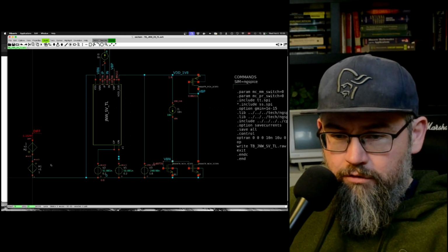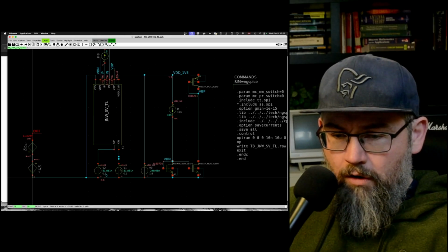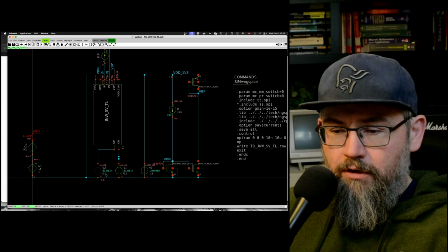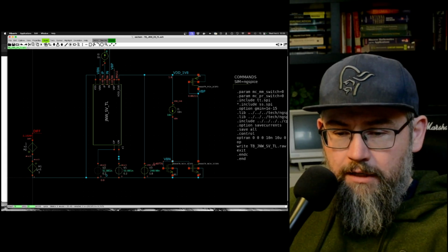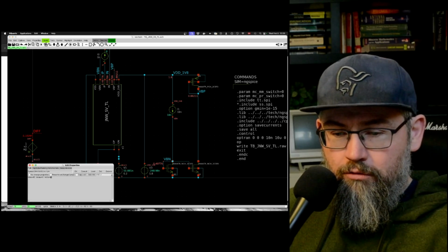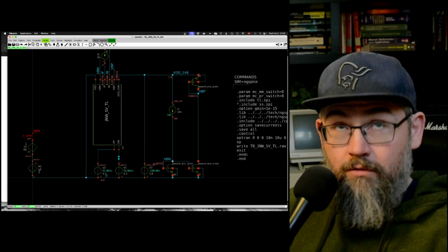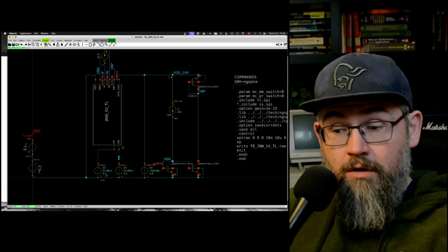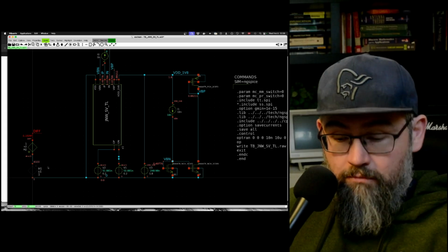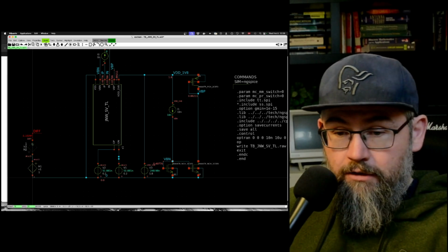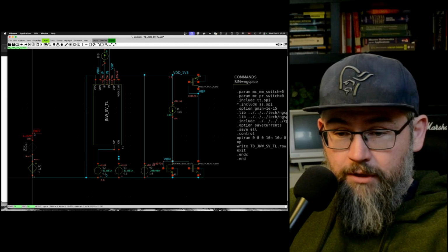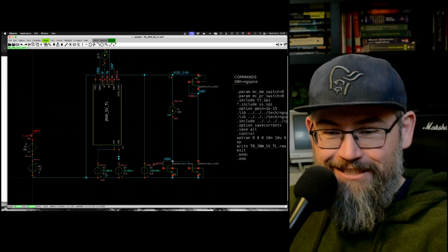Okay, first of all, in order to compute the difference between the current in these two, I take a current controlled voltage source and take the current from V1, right, and take the current from V2 and just go plus minus to get the difference. Okay, so that's why I get this up here.